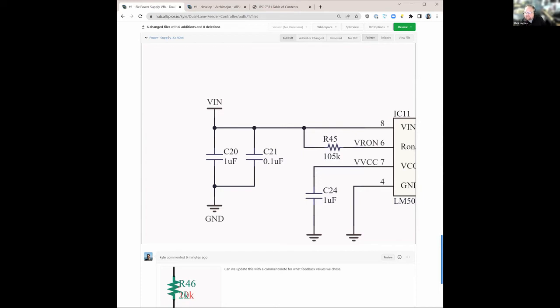I believe that is what Mark is asking. Mark, if you want to clarify that, please do. And to take it to another level, what assembly technique are you using? Are you going to use solder paste and reflow? Are you going to do wave solder, selective solder? Are you going to do hand solder? All that type of thing, it does impact your design. So I think that is what he's asking.